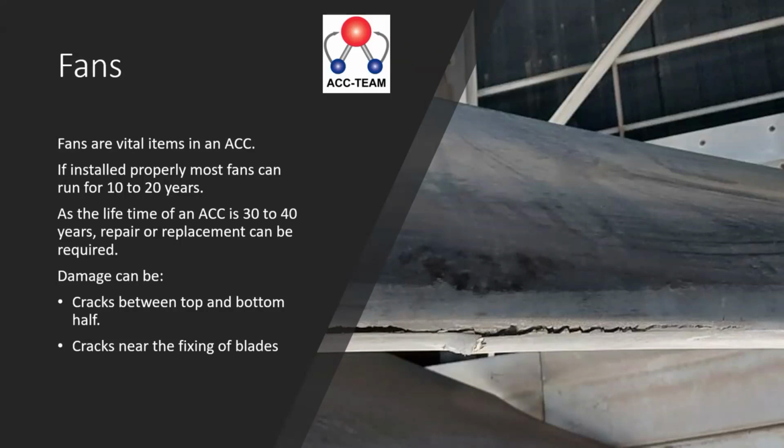From this example, we found out that it is quite important to have regular checks, I would say at least once a year, to inspect the blades to see if there are no cracks. There are very simple tricks and ways to do that and to prevent possible failure of the fan. Because if the fan loses one blade and the vibration monitoring system is not working perfectly, you get quite a lot of damage. So this is just something that we found in practice, but it was not the only one.